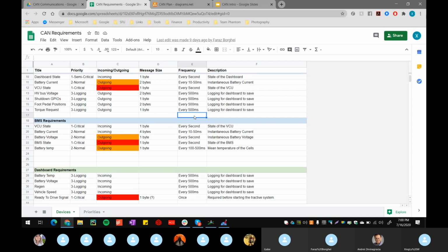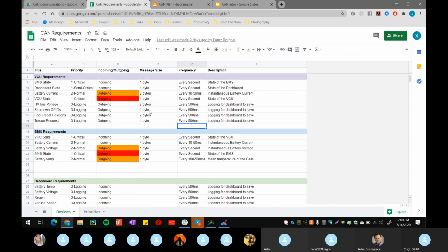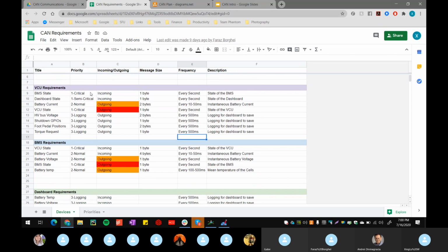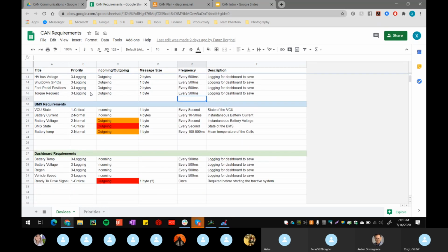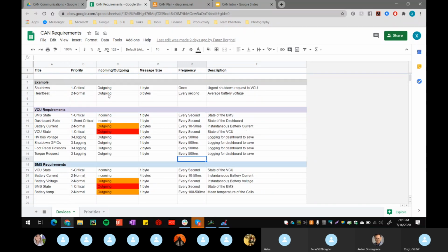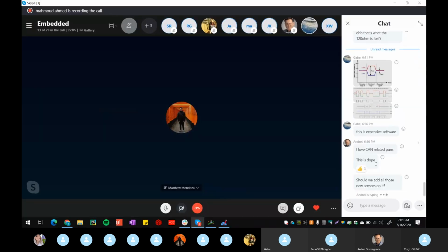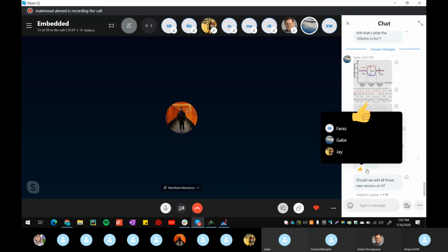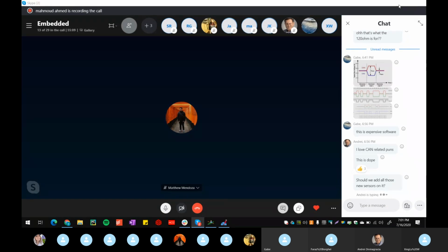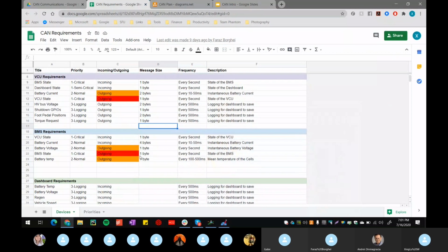Someone else needs to go in here and put all the charger commands, right? Yeah, that would be separate because it would be a completely different state. I can add it into the same DBC with no problem, but right now it's mostly focusing on vehicle running, and then doing CAN charger later. Makes sense. All the new sensors would go inside here, like the tire pressure, ride height, everything.